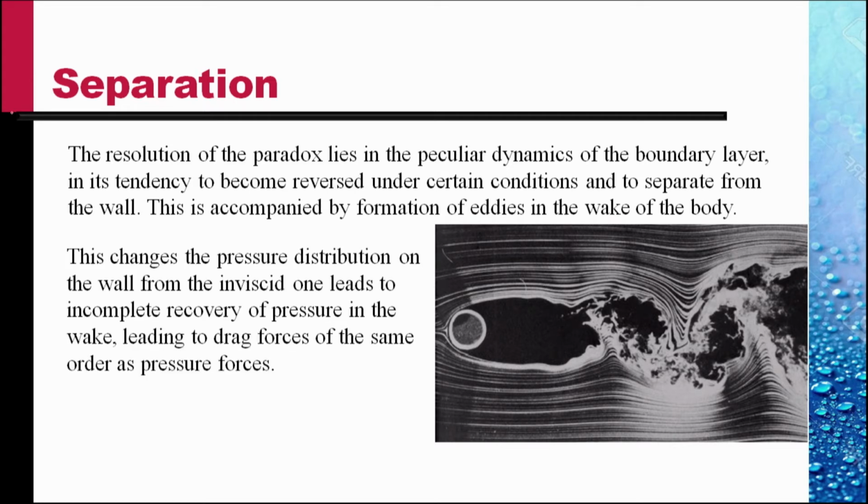This changes the pressure distribution on the wall from the inviscid one and leads to incomplete recovery of pressure in the wake, leading to drag forces of the same order as pressure forces. Thus, the separation of the boundary layer on the surface of a body makes the flow disturbed and the pressure does not recover back to its original level in the wake of the body, and thus a pressure drag results.